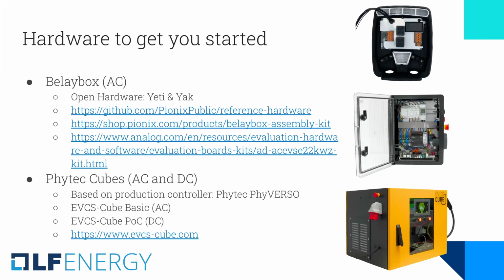Okay. And related, how does libOCPP internally process remote start transaction when authorized remote TX requests is set to true? Specifically, what's the authorization flow? Does it first call the authorization callback, then check local authorization list, and finally send authorized to CSMS?